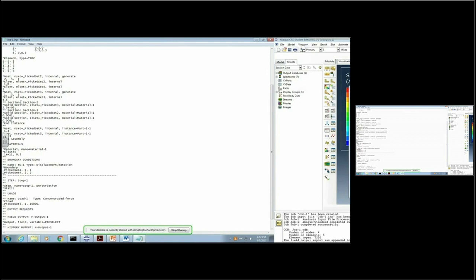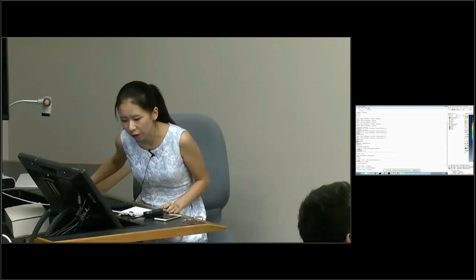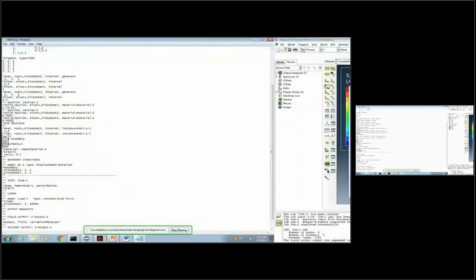And then for element 2, for example, right now if I want to change the cross-section area of the vertical truss, because the vertical truss has only very low compression, right? I can reduce the cross-section area. And then for horizontal, I need to increase.